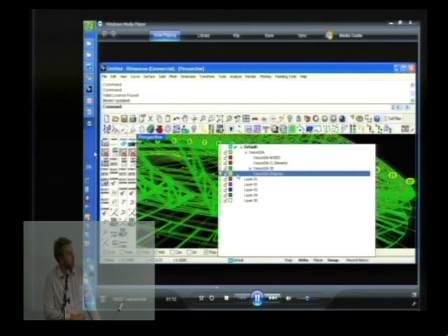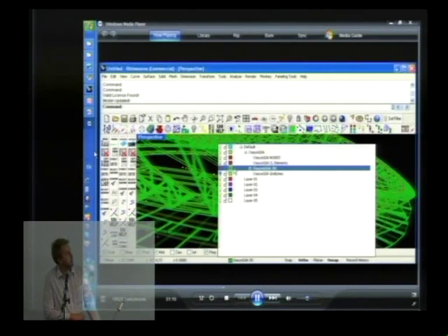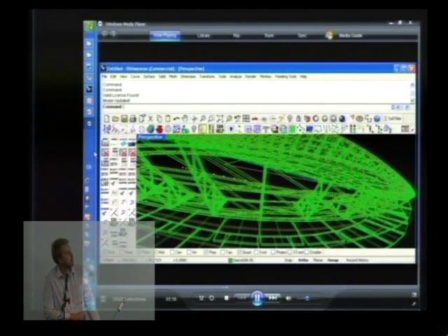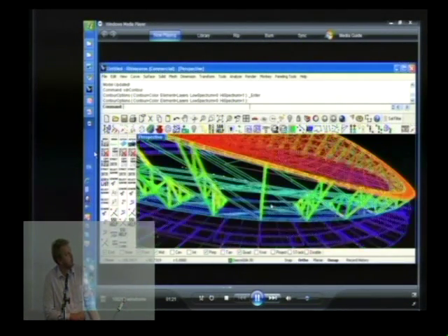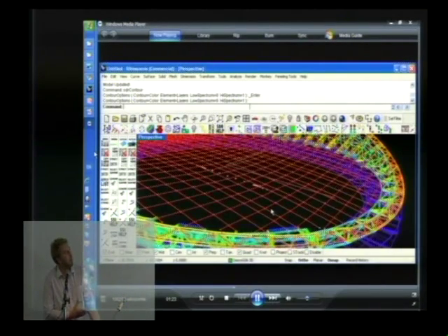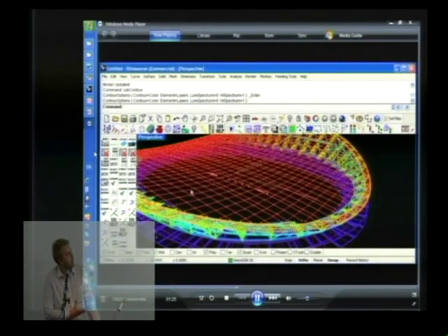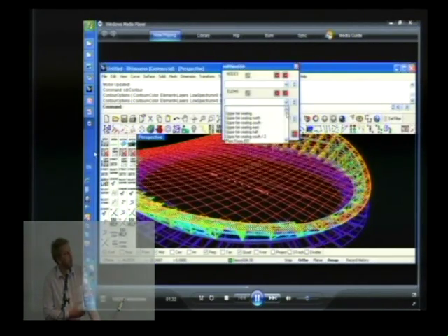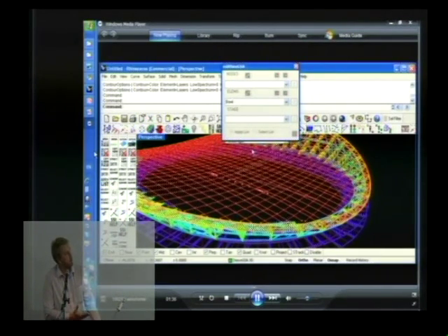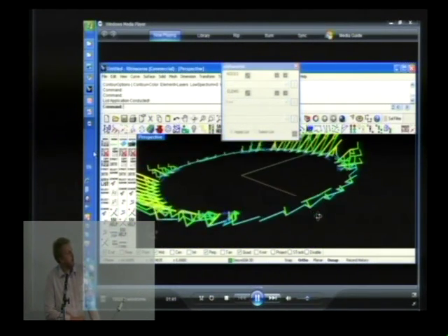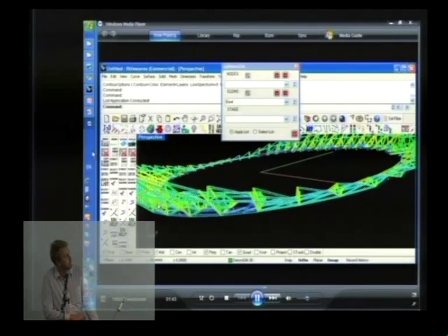So there is the ability, effectively, I've opened up here the structural analysis model, which we use the ARUP program, GSA, to assess the strength and the amount the stadium moves. And then you do have the freedom and the flexibility to do all your geometrical manipulations in Rhino, which are not so powerful in the native structural analysis program, including working on groups or subsets of your model. Those lists can be used in the different environments, the same as you can in your structural analysis program.